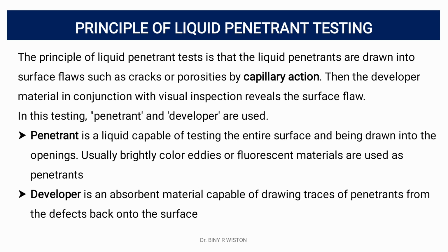So there are two components which will be in use during liquid penetrant testing, namely the penetrant and developer. Penetrant is a liquid capable of wetting the entire surface and being drawn into the opening. Usually a brightly colored dye or paint or fluorescent material is used as penetrant. Whereas developer is an absorbent material which is capable of drawing traces of penetrant from the cracks back onto the surface.